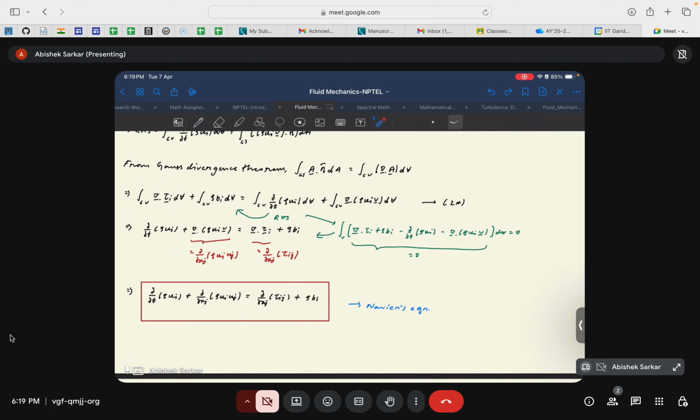The most generalized form is indeed the Navier's equation or the Cauchy momentum equation. This equation is still in terms of the shear stresses. Modifications on the shear stresses are made by considering assumptions such as the Stokes hypothesis and the Newtonian fluid, which make this Cauchy momentum equation the much celebrated Navier-Stokes equation.